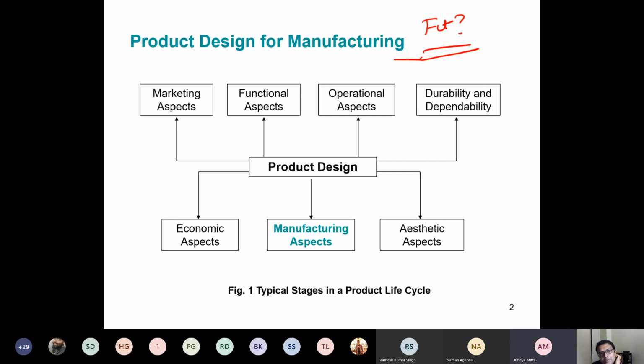I think we read about three types of fits based on the shaft diameter and the diameter of the bolt or the nut, I think. Hole is fine. Nut you don't need to worry about. It's just a hole and shaft. So what kind of three fits are there? I think clearance fit, interference fit, and there's a fit in between, so transition fit, I think. Yeah. So clearance, very good. Clearance fit, interference fit, and transition fit. Right.